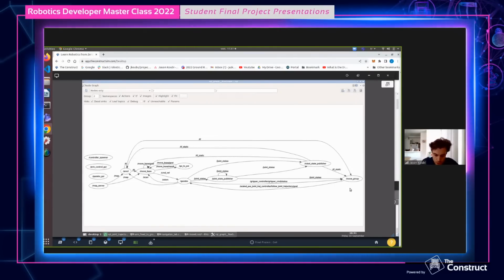I remember it basically uses the odometry message and 3D visual odometry from a camera, but I was more interested in using the GPS, because the mission is outdoor and it will be long distance. So I think it's better for me to combine the GPS with the IMU and use an EKF, extended Kalman filter, for noise reduction. Okay.